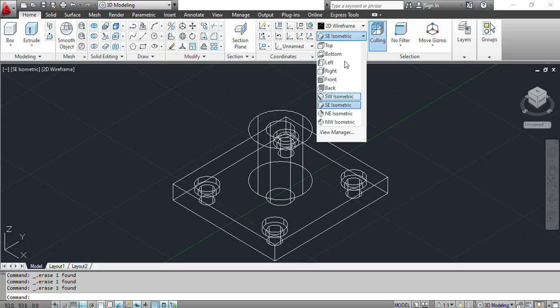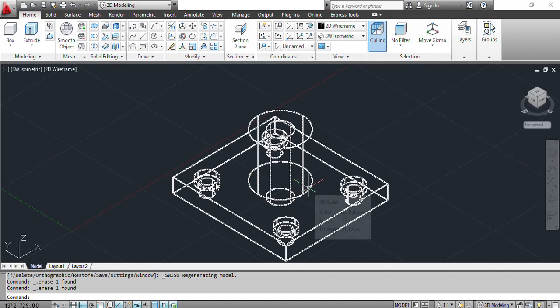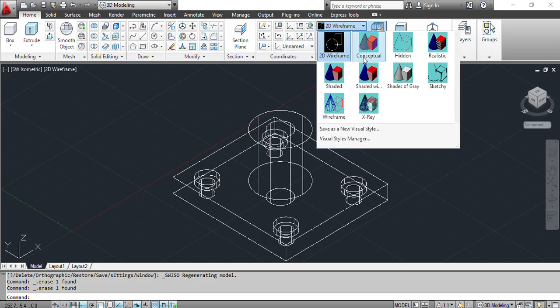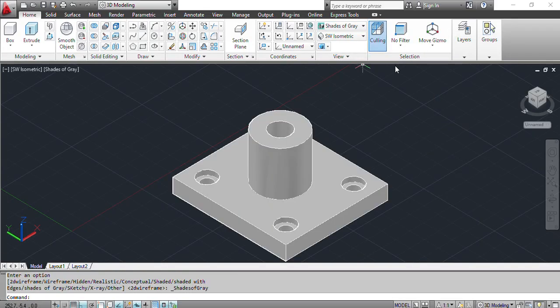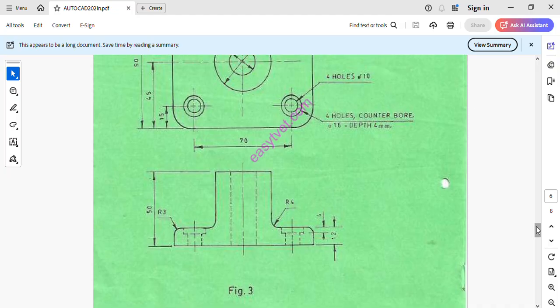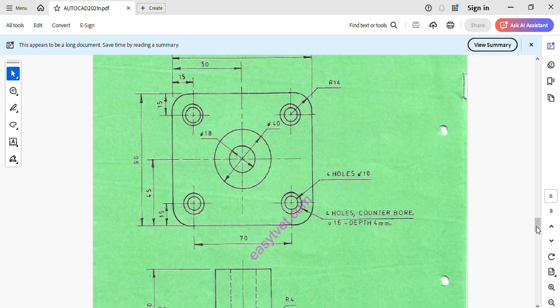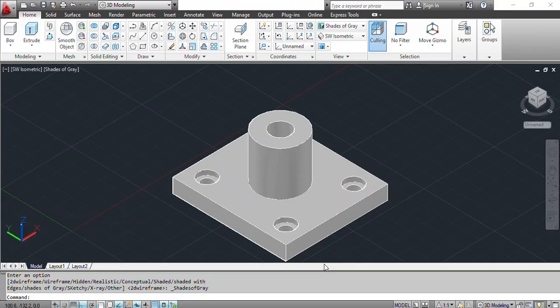So after doing that, we want to get to the fillet, but let's check. This is right. Let's get the fillet, and in filleting we have the fillet to be R14, according to the specifications given, according to the dimension there it is R14.